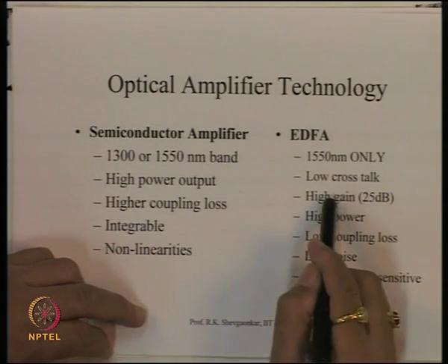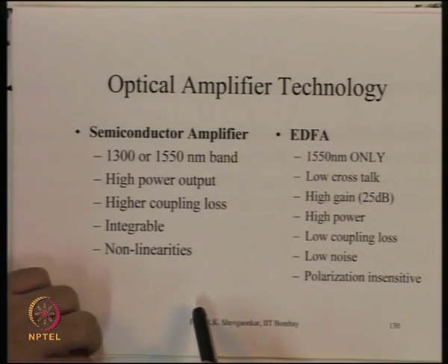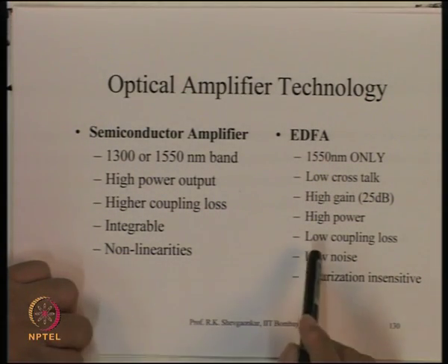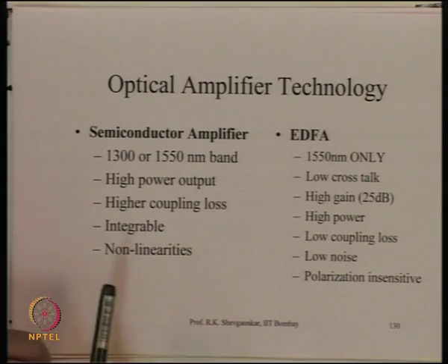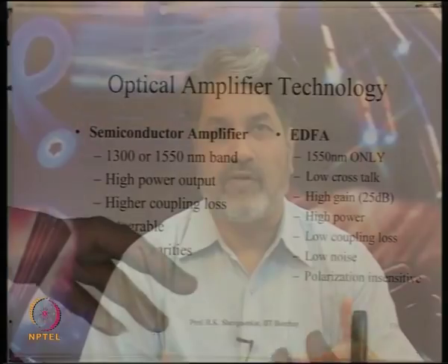But the biggest advantage of EDFA is it is completely compatible with the optical fiber. In fact, this amplifier is built inside the optical fiber. We will see later how this amplifier works. But basically the same fiber, if you dope with a material which is erbium, you can create an amplifier inside the optical fiber.